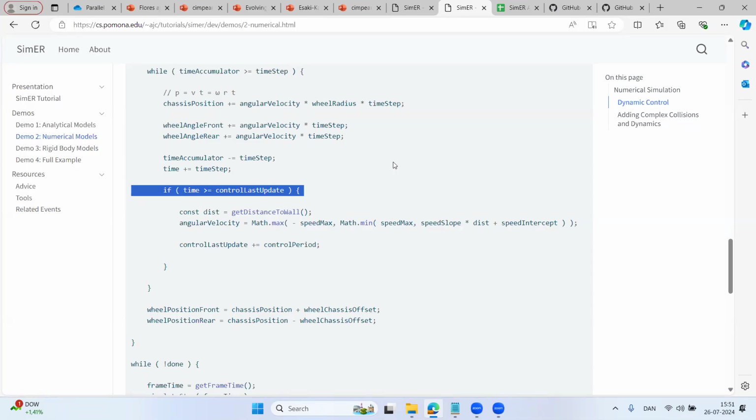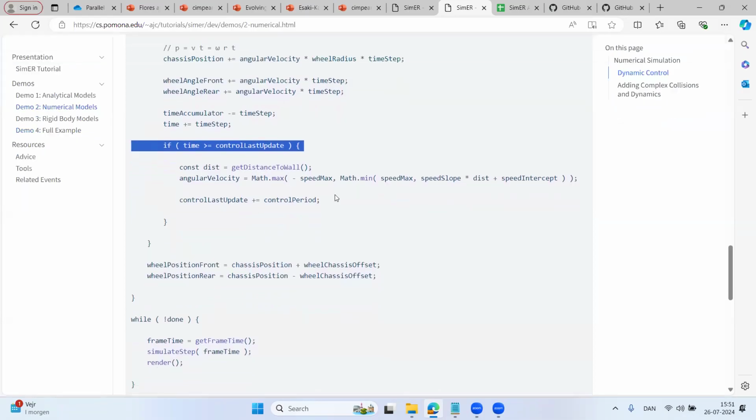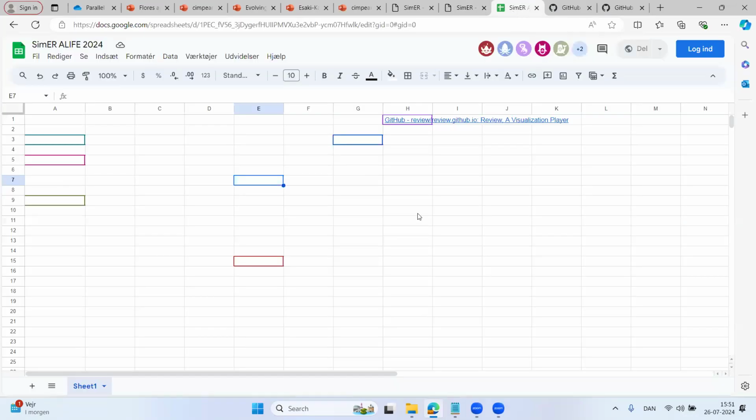So for example, when I have a wheeled mobile robot, if I'm going to put this controller on a real device and have it go up to a wall and try not to run into a real wall, if it's running on a microcontroller, like an Arduino, I can probably only update the controller 100 times a second. So decoupling those two things is one of the first things I would say. That's probably different than anything you've heard before. My first sort of practical advice. Any follow-up questions from anything that I just rambled on about there?